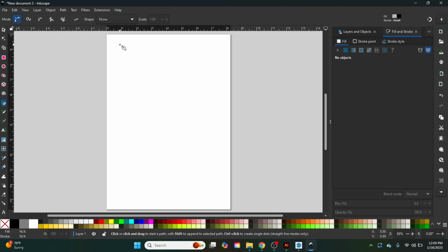And in my drawing, I can literally go down. I can hold control, which makes it like a 90-degree or a 45 in different increments, which is actually pretty nice. If you go down below, you can see the distance that I'm traveling. And if I wanted to get my 36-inch piece, let's say this was 36 inches, I let go of control, I click, it's straight, it's 36.